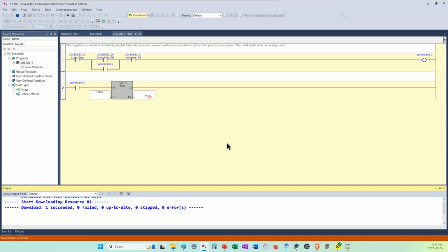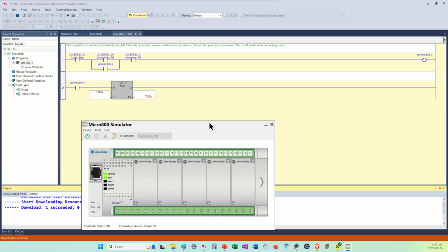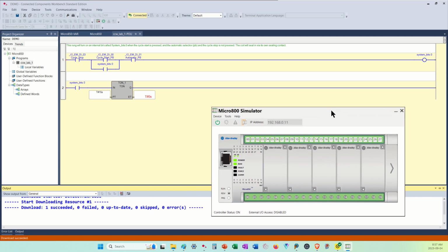The background has gone to this buttercream color, and everything is blue except our elapsed time, which is in red and says 0. So this is where a simulator will help us out. So I need to have DI03. If I click on that, that's like me physically pushing the button, or in this case, because it's a stop button, I'm saying it's wired up.